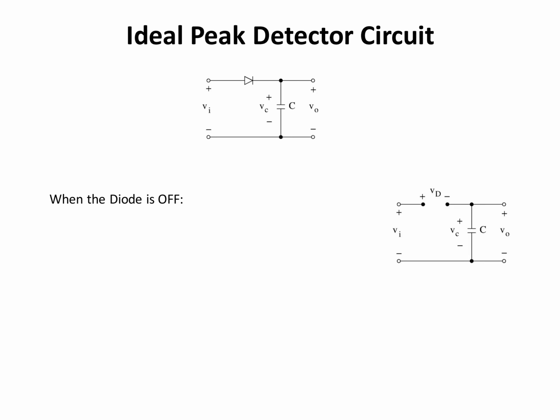So let's write the equations for the diode being on and off, and find the equations for the output voltage and the conditions of the diode being on and off. When the diode is off, I know that ID is going to be equal to 0, and VD is going to be less than or equal to VD naught. In that case, using this KVL, I know that Vout is going to be equal to VC, and that's a constant value.